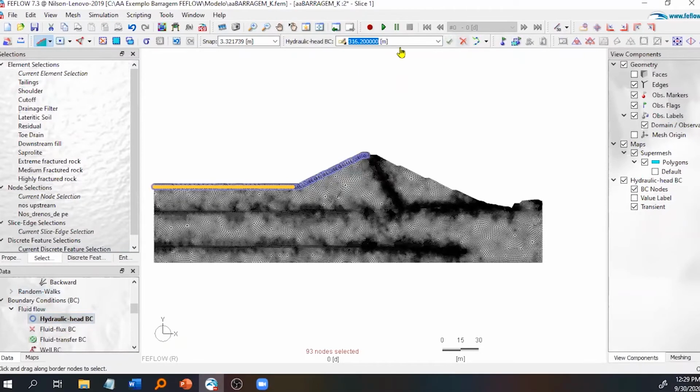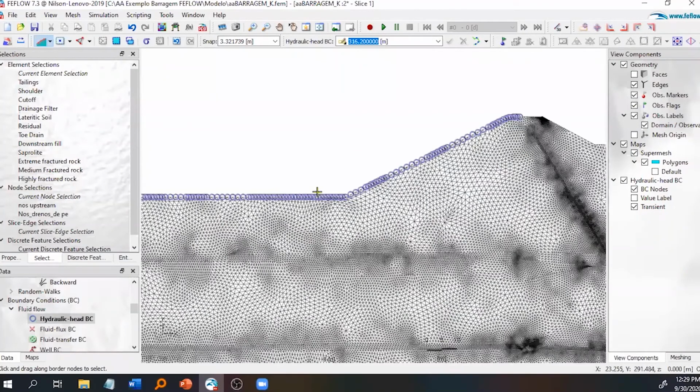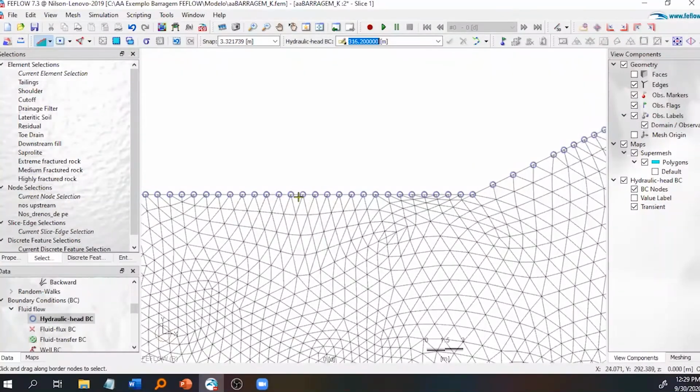Now I can see everything. That's tricky because in FEFLOW, one has to pay attention to what's bold, because sometimes you are doing something, nothing happens, then you see, oh, this is bold, so it's only assigning to where it was bold, the shoulder. Now it's okay. And what we can see is these nodes have the circle, meaning those are boundary conditions equal